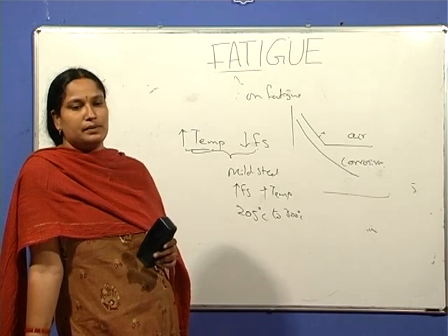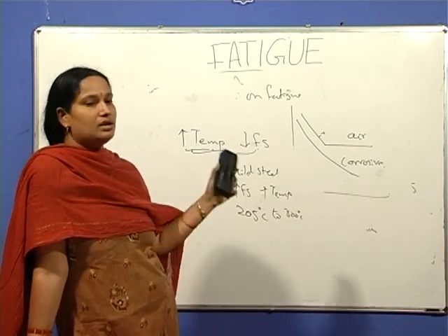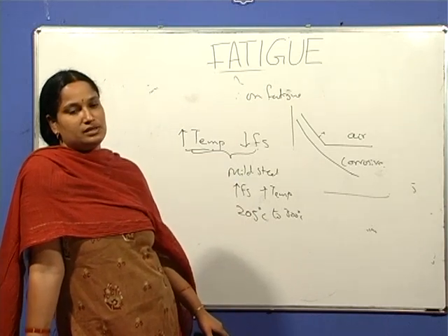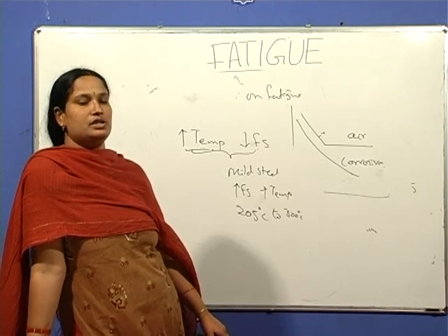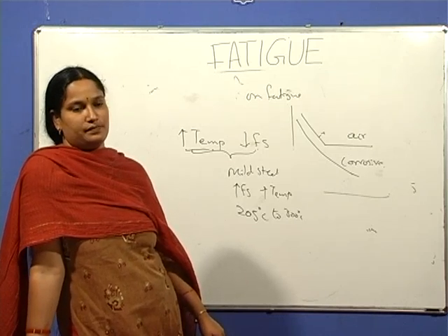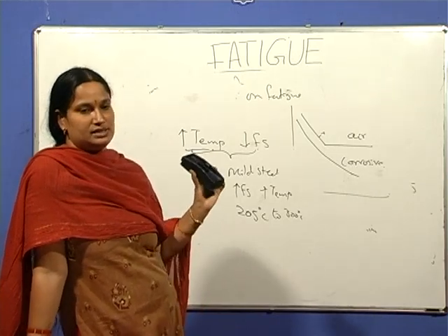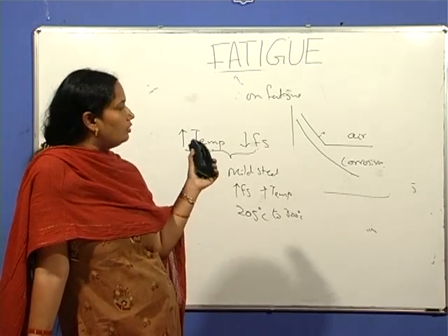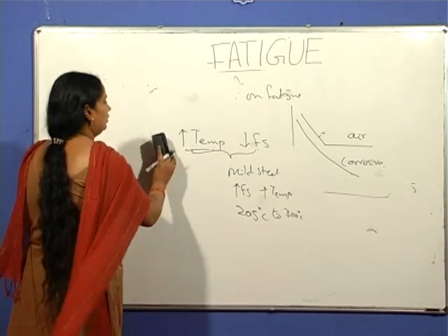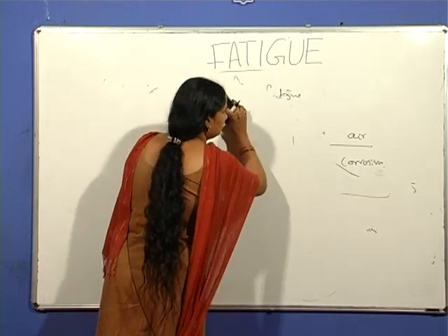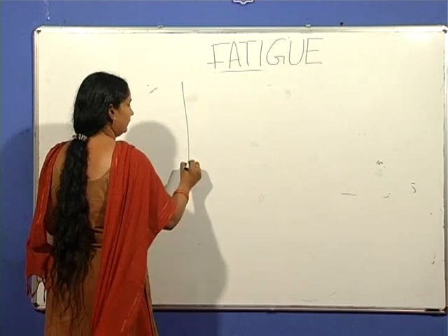Because of large plastic strains, they mask the compressive residual stresses, which is known as fading of residual stresses. So, these are some of the environmental effects on fatigue. And moreover, the endurance limit which is seen for materials like mild steel,